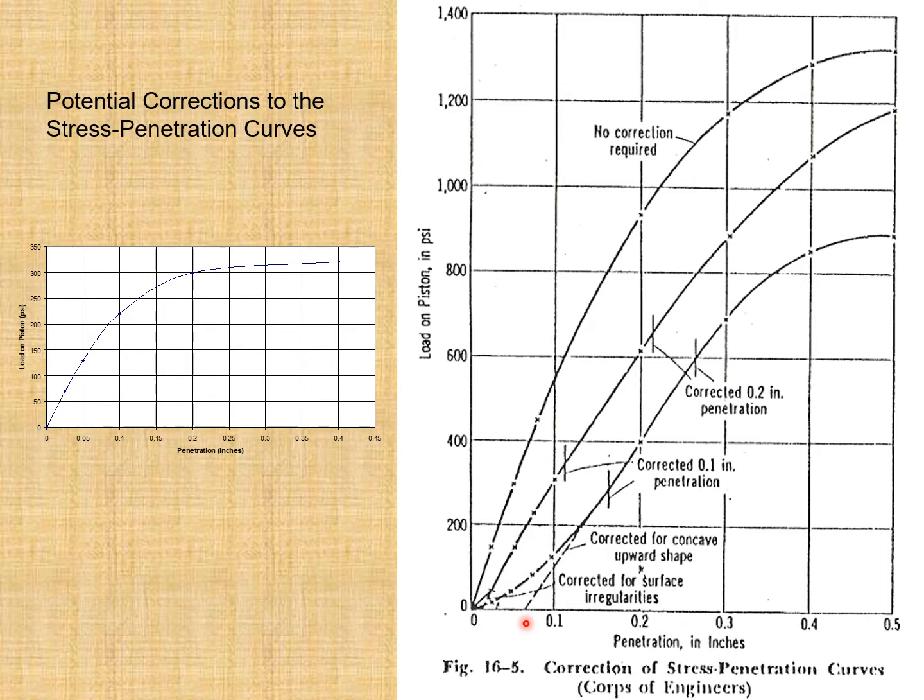And from this 0, considering the scale that we are using along the horizontal axis, 0.1 will be somewhere here, 0.2 somewhere here, and 0.3 will be somewhere here. So by using the new scale, we will determine the load or pressure corresponding to 0.1 inch penetration and 0.2 inches penetration, and in this way we can determine the CBR values.